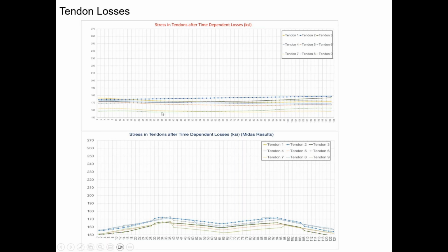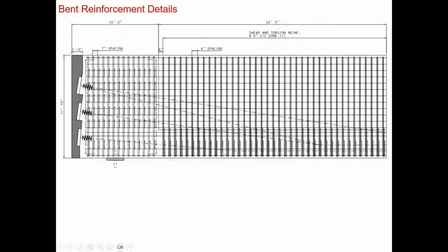We still have some differences in the profile or in the values here on how the shape of the stresses look like, but at the end of the day, the values are pretty much comparable at the main sections and the critical sections of the bend. So of course, when you end up the design process for the bend, you end up with something that's hilarious like this, with huge amounts of steel. This is happening for the end anchorage, vertical bursting reinforcement, horizontal reinforcement.